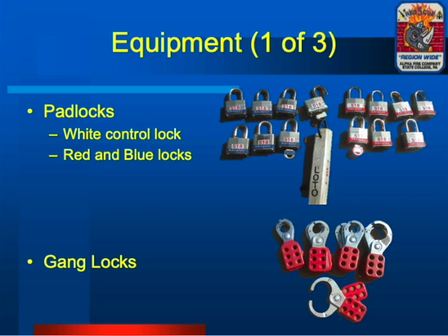How we operate with these: if you put a lock or a gang lock on something, then you take that key, and that key either goes in your pocket or it goes to command. If we're using multiple keys and multiple locks, we're going to lock out with multiple locks. So we're going to use multiple blue and multiple red.